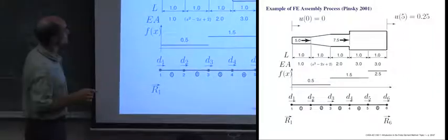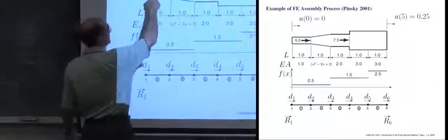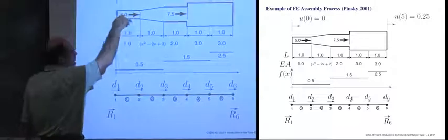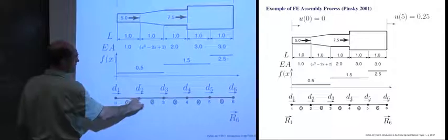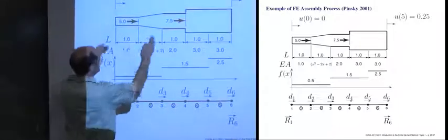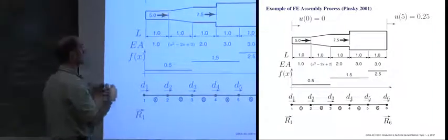You see there's one other thing we did that makes our lives a little easier, which is wherever we have a change in either the geometry or we have a load applied, we put a node. So that's by choice. We actually don't have to do that. There is a way to, you start to lose resolution, but it'll still work.